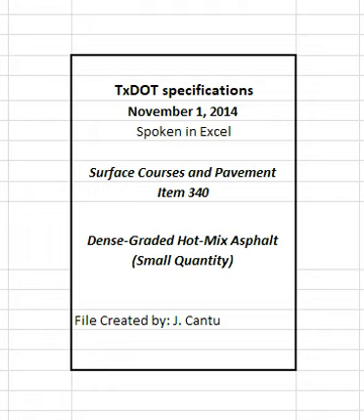2. Materials. Furnish uncontaminated materials of uniform quality that meet the requirements of the plans and specifications. Notify the engineer of all material sources and before changing any material source or formulation. The engineer will verify that the specification requirements are met when the contractor makes a source or formulation change, and may require a new laboratory mixture design, trial batch, or both. The engineer may sample and test project materials at any time during the project to verify specification compliance in accordance with Item 6, Control of Materials.